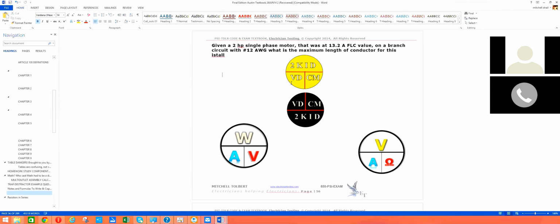Yeah, so right. Voltage should be the same, right? That's right. So it should be the same at the starting point, at the end point, and all points in between. So when you run a distance on a small conductor for the load that it's carrying, then you do get a little bit of voltage drop over the conductor, and that's line loss, branch circuit loss, or could even be a feeder loss if you have a severe enough load on too small of a feeder. Either one of those, that's what these 2 formulas up here deal with.